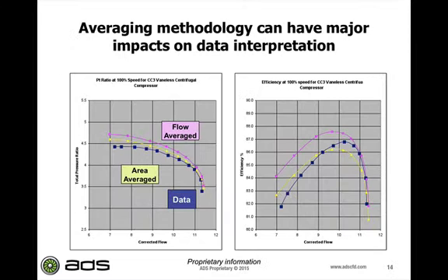Okay, next, I also want people to be aware that CFD simulation results also depend on how you average the data, as shown in the next chart. In our CFD code, we generally average the data using mass average. So when you compare the total pressure ratio, you are comparing the mass-averaged total pressure through all the computational planes. This time I simply want to show you what the difference is if I do an area average, with the same set of data but two ways of averaging.